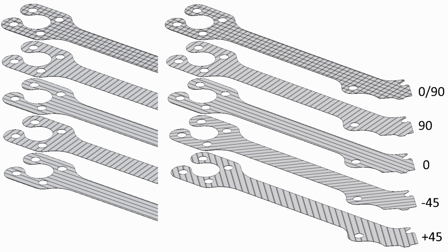So right, because it's the actual resin. That's why the carbon fiber splits at the ends when you stub it against the ground or crash. The end of it is frayed because of the resin in it, right? Yeah, resin is very weak compared to the carbon fiber. I think it's a factor of 1 to 50 or something like that. The fibers only have strength in a single direction. They're totally useless in all other directions. The resin is more or less what's holding everything together in all other directions.